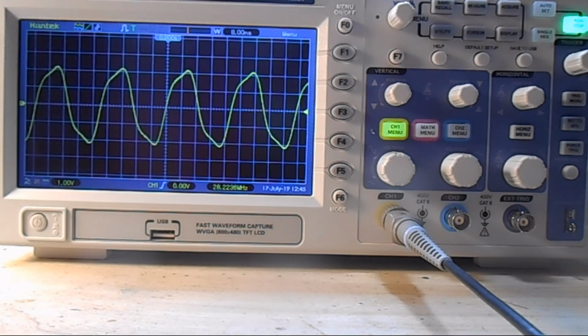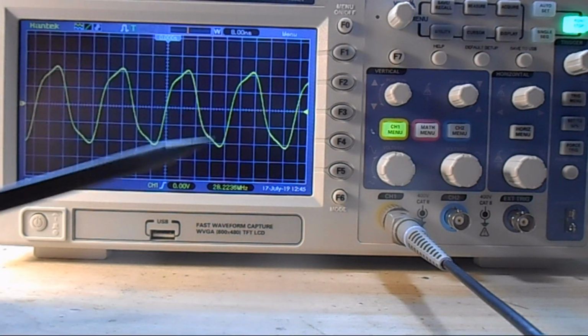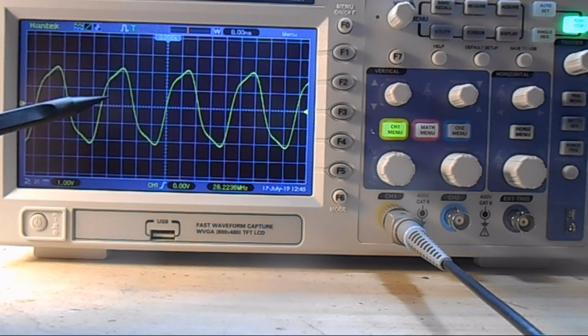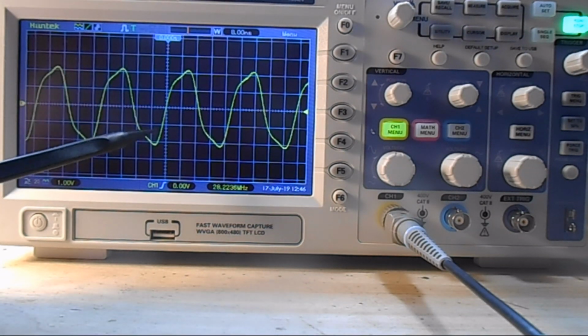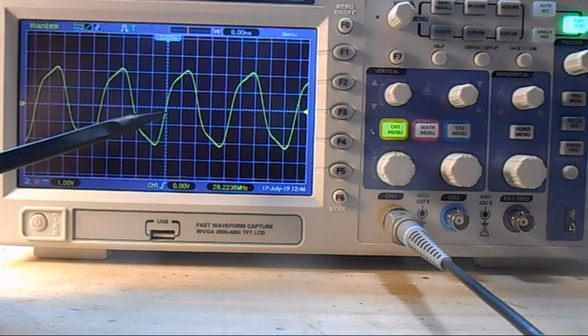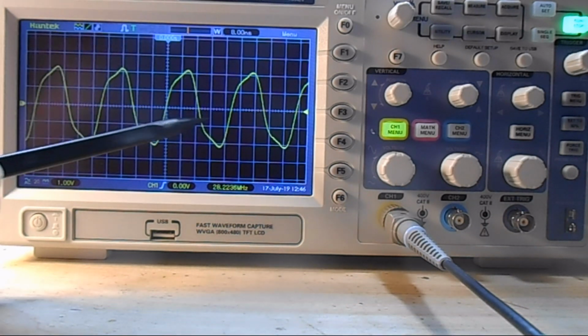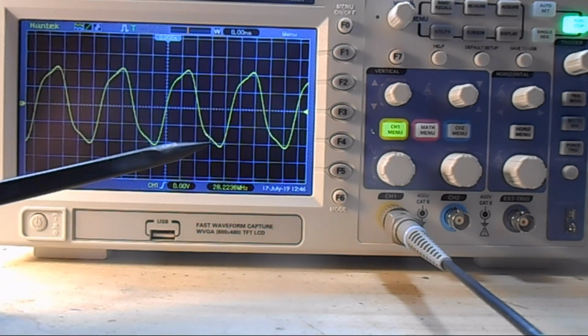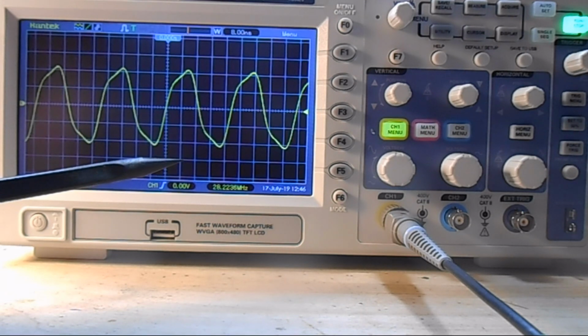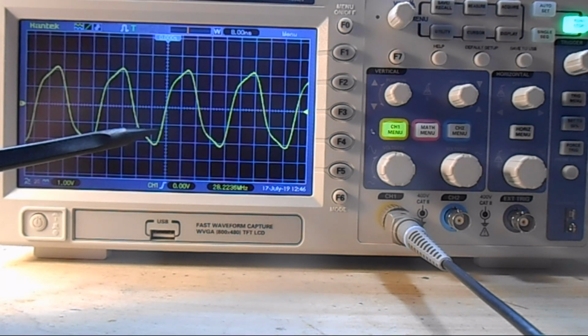So, moving along. An oscilloscope is simply an electronic test instrument that displays an electric signal over time. Here on the y-axis, the vertical axis, you are getting the amplitude component of the signal, which in most cases is the voltage. And then on the x-axis, we get the time aspect of our signal.